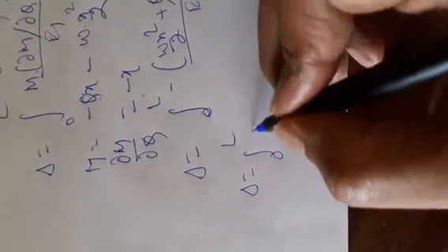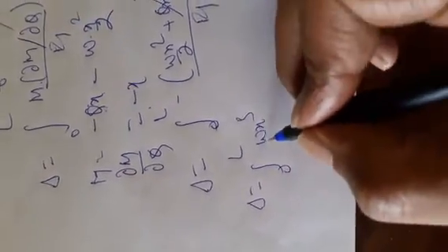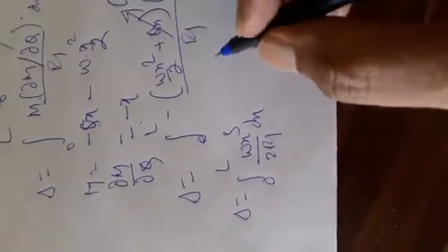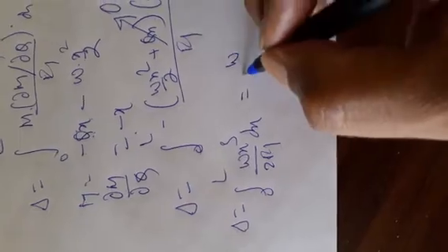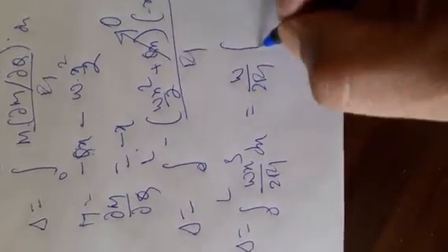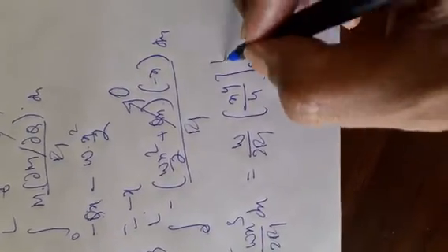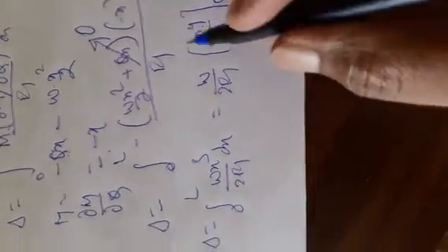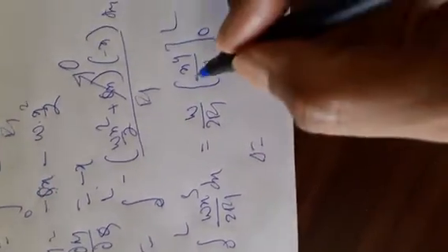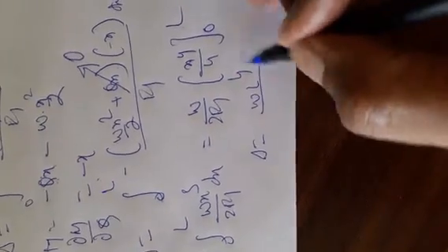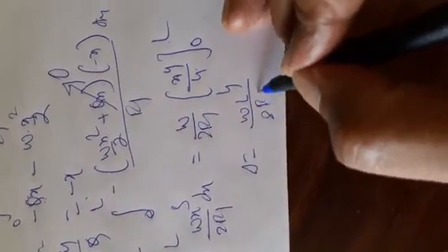So I am left with delta is equal to integral 0 to L of Wx cube by 2 EI dx. So integrate with respect to x. So W by 2 EI into x raised to 4 by 4, 0 to L, and this gives me the answer. Delta is equal to, substituting x equal to L, W L raised to 4 by 8 EI.